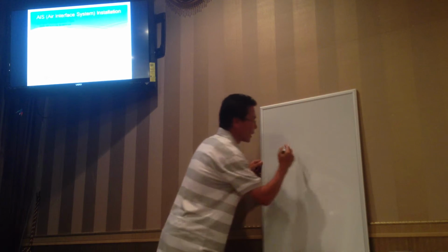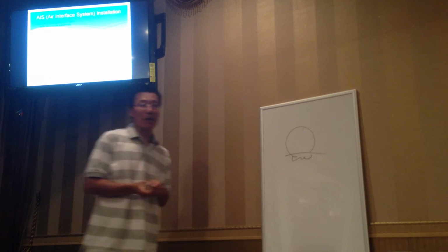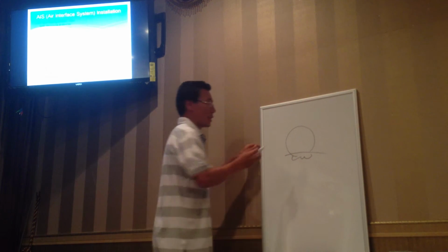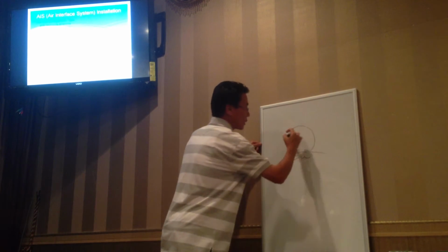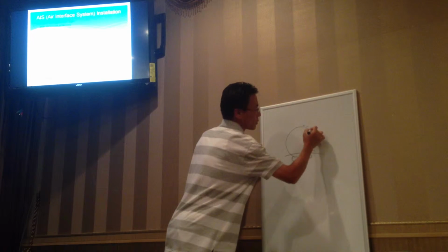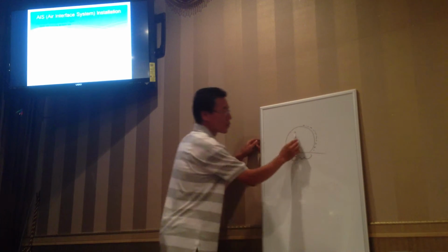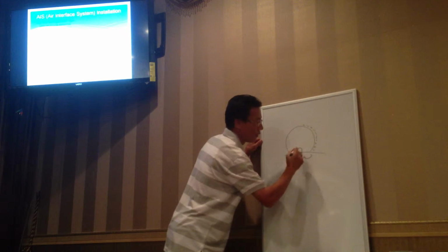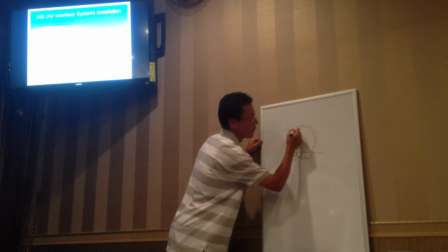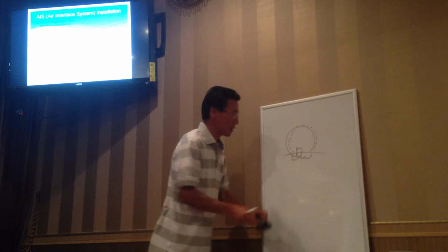And beam steering, azimuth steering, is a horizontal pattern control. So this is the coverage. We like to cover this area more. If there's a customer complaint, hey, I have pretty bad service here, they can rotate the antenna to this direction, right? That's beam steering.